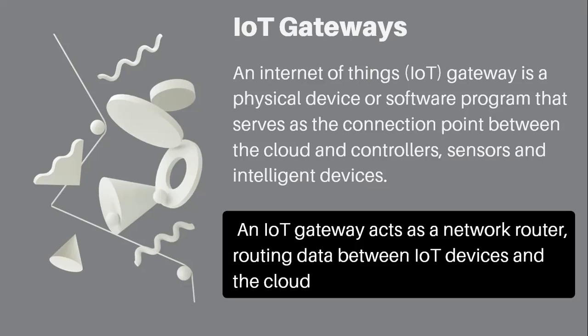Now, there are special IoT gateways that you can make use of, but they may be quite expensive for you as a beginner. So you can get your ESP32 microcontroller, which has a Wi-Fi module in it. In your program, you enable the Wi-Fi module, and then you save the credentials of a particular router or Wi-Fi hotspot, the hotspot name and the hotspot password, in your ESP32.